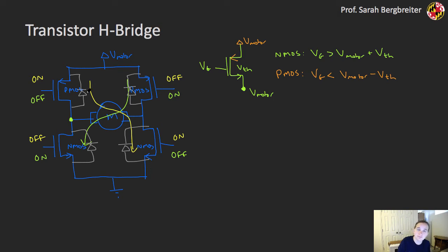If I were to use NPN and PNP transistors instead, which I can absolutely do, in that case I typically want to include an additional diode around those transistors to provide that flyback diode. But you can certainly always add those diodes, and that's probably the safest thing to do, but for the most part those can often be built into the MOSFET transistor.